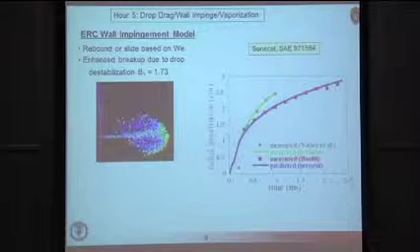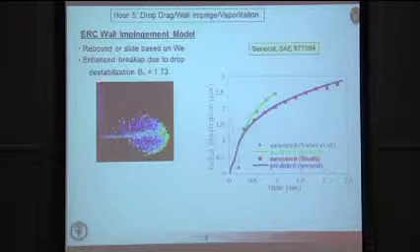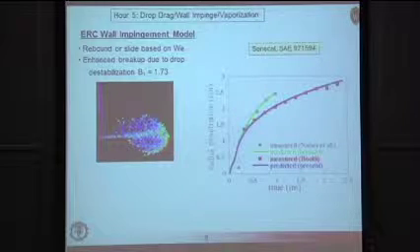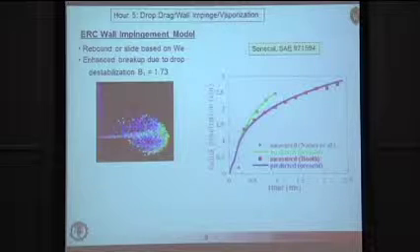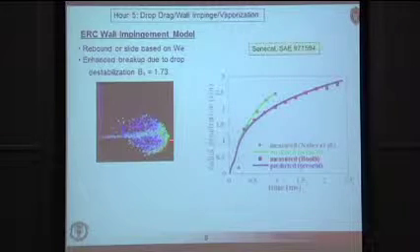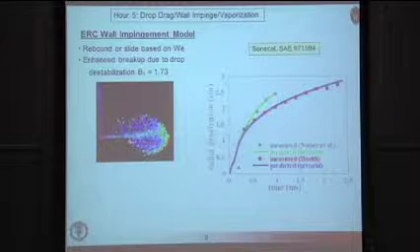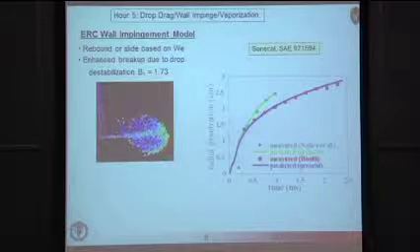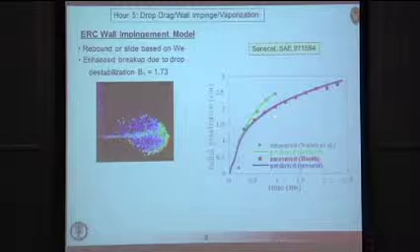And this just shows some validation data that we did for a very simple but effective experiment, where we have a nozzle injecting a spray down onto a target, which in this case was just a flat pedestal arrangement. And then we measure the penetration of this deflected jet as a function of time, and we get plots like this. This is the penetration of the jet from the axis of symmetry here as a function of time. You see the lines are predictions, the symbols are measurements for two different cases. And this actually works quite well.